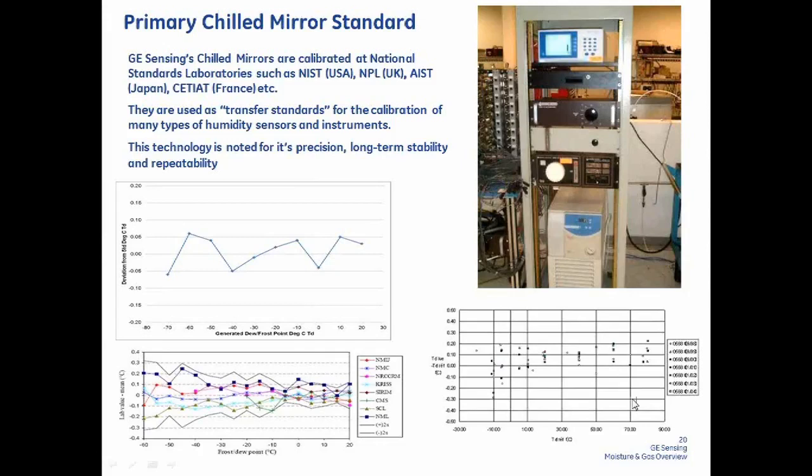There are many processes where a few parts per million is too high for that process. For example, in ethylene production or in natural gas or LNG production, typically they may have alarm points in the neighborhood of 1 to 20 parts per million.